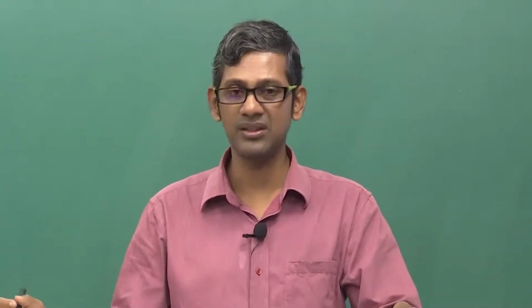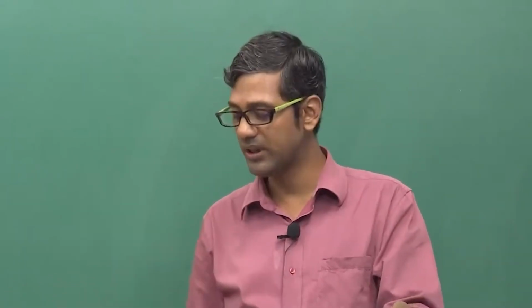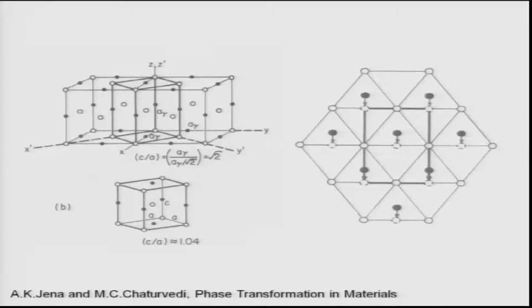So, these planes actually remain undistorted, and that is only possible when you have shear-like deformations. So, what actually happens is what is shown in the next picture which I have shown you earlier. If I have continuous FCC austenite unit cells sitting in a manner atomically, where these white or open circles correspond to iron atoms and the closed black circles correspond to carbon atoms, what we can do is constitute a BCT unit cell out of the two FCC unit cells, just like the way it is shown in this picture, and the one which is taken out from the construction is shown here in picture B.